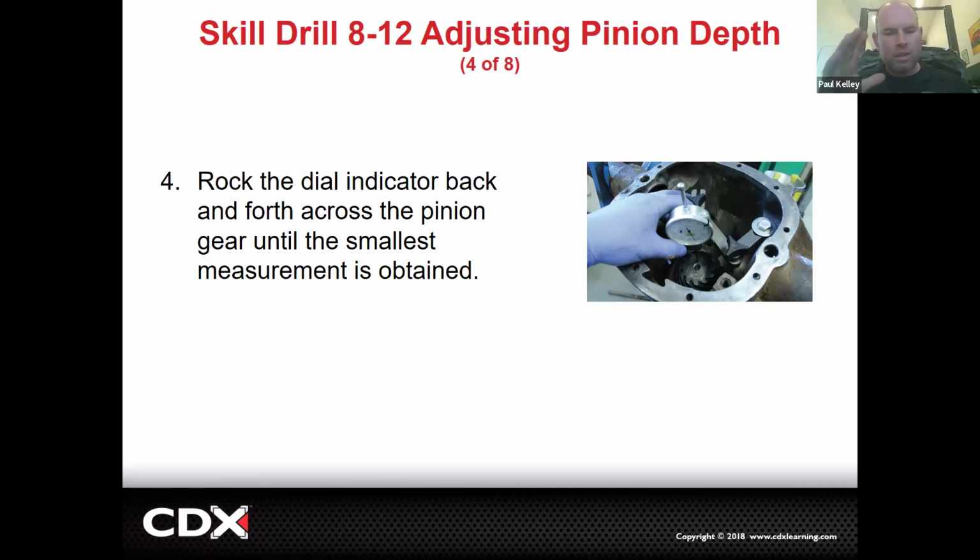You still have to set the pinion preload. You still have to get the ring gear and stuff in. You still have to set the total preload and the backlash. But then when you paint it, it's more of a formality. You're not painting it to see if your pinion depth is right. You know your pinion depth is right. But again, I'm not exactly sure why, but not in Toyota land.